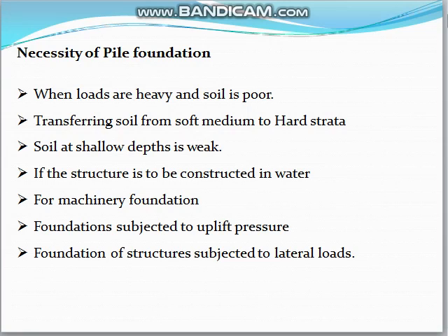After site clearing, the next step is locating the footings. After locating the footings, we have the excavation, that is the digging. Then in the open excavation, at a normal shallow depth, if you get a hard strata, then it is the shallow foundation. If at a shallow depth we are not getting a hard strata, then we go for the pile foundation.